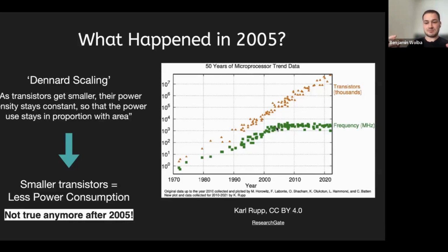So transistors still got smaller, but their energy consumption and heat dissipation did not reduce in proportion as you would expect. And so Dennard scaling broke, which means heat became a much more severe problem for your microchip. And even today, it's most often not the actual transistor that's the bottleneck for compute, but rather how do you get rid of all the heat that is within your microchip? Or how do you supply data to the microchip, that is your memory, that is limiting you?